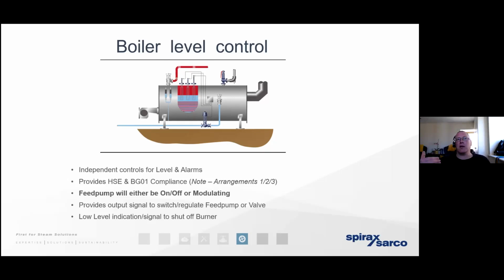So if we've got a boiler that is producing steam at 10 bar gauge, where boiling point is 184 degrees, if we're bringing water from the hot well at a very, very low temperature, 50, 60 degrees, that huge mass of water being brought into the boiler is going to create a lag or a fall off in the steam production rate. And that may cause problems for the process, for the production.